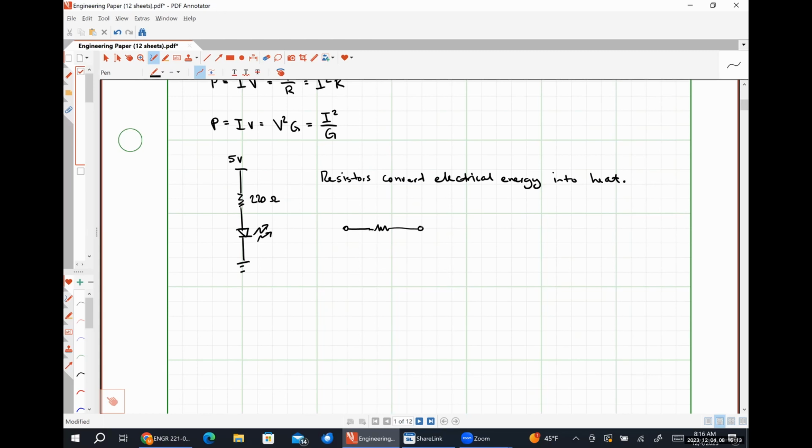So if we have a resistor and we have the voltage drop across the resistor like so, with positive polarity on the left, and the current I is flowing into the positive polarity terminal, then we are going to use Ohm's law as V is equal to I times R. However, if we have this situation where we have our resistor, now let's put the positive polarity terminal on the left and the current flowing into the negative polarity terminal.